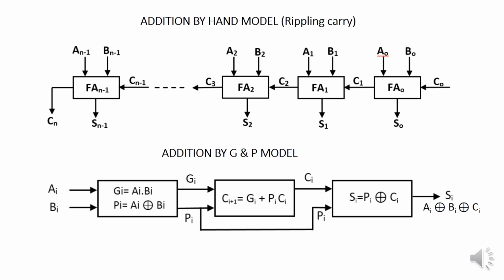Now, the carry generate scenario and the carry propagate scenario have given the idea of drawing the circuit for the summation in another way. This new way consists in dividing the addition process in 3 steps corresponding to each of these equations. First step, second step, third step.